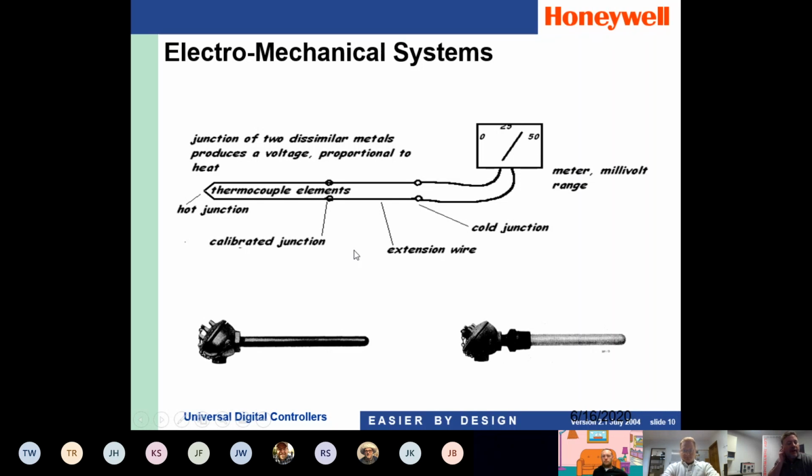So a lot of different styles of thermocouples. You can have thermocouples with cast iron heads, aluminum heads. You can also just have a quick junction connection on the outside to make it easy to replace the thermocouple if one goes bad. There are a lot of different protection tubes based on what type of application you're putting the thermocouple in. You have ceramic tubes, Inconel tubes.